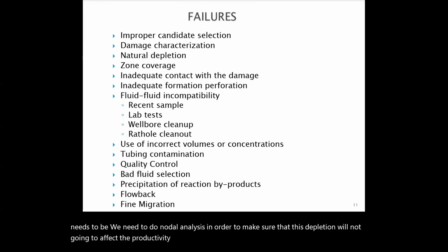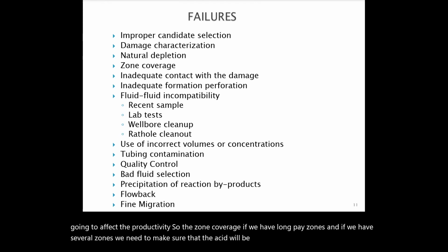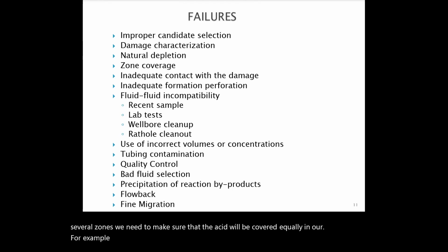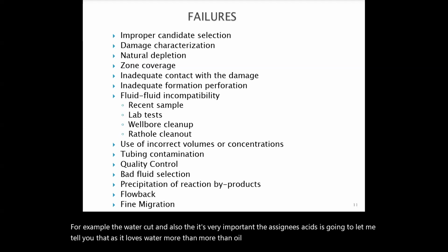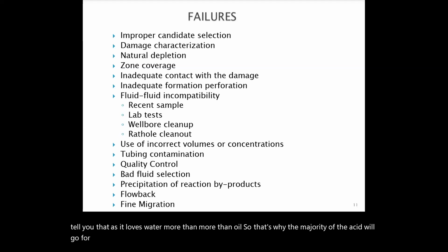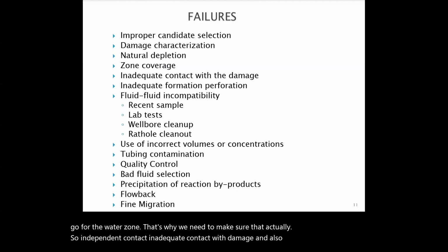So the zone coverage: if we have long pay zones and several zones, we need to make sure that the acid will be covered equally. For example, the water cut is also very important. Let me tell you that acid loves water more than oil. So the majority of the acid will go to the water zone. That's why we need to make sure of this. Also inadequate contact with damage, and also formation, perforation, fluid incompatibility.